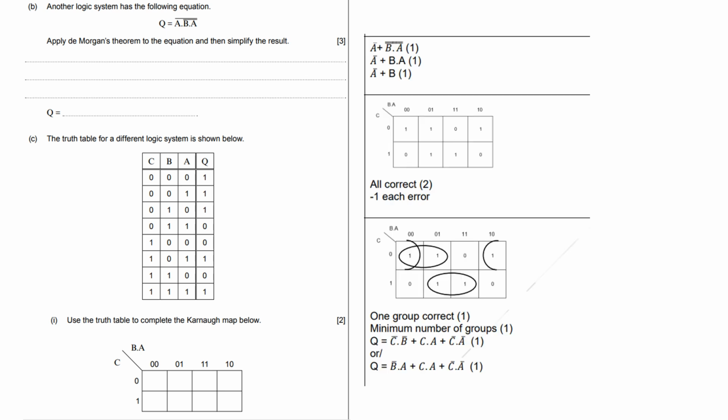Okay, just have a little look there. Let's get the laser pointer, shall we? So you can see split the line, change the sign, double knots cancel. So you're left with that. This is a Boolean identity, but if you multiplied this not A into that bit there, you'll see that the not A or A would cancel. So you'll be left with that. So it's 3 easy marks.